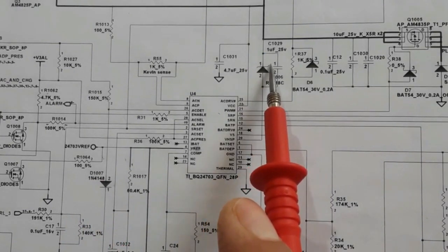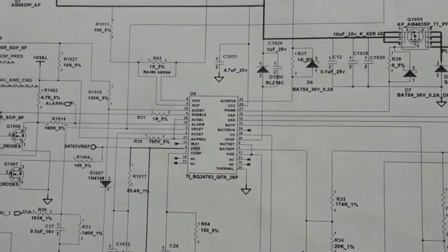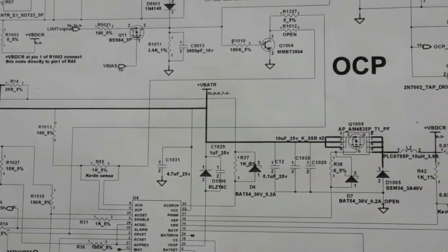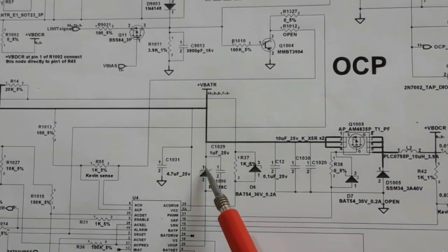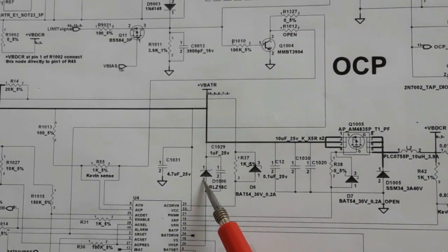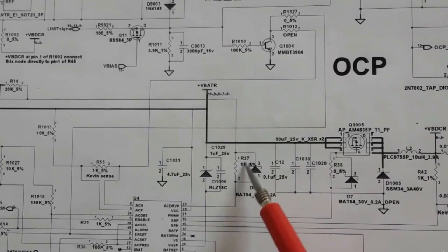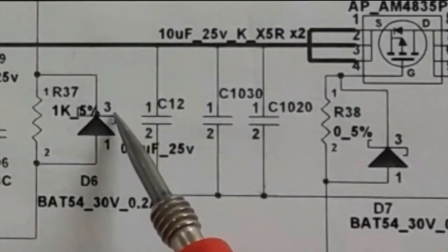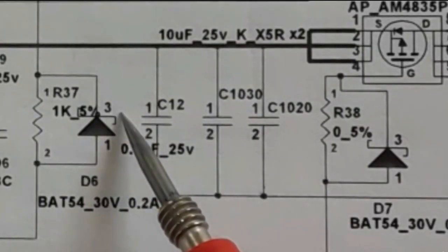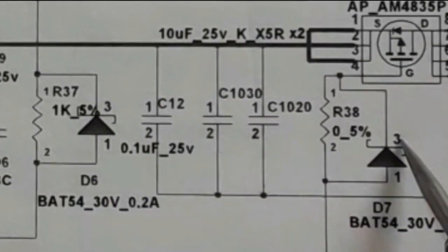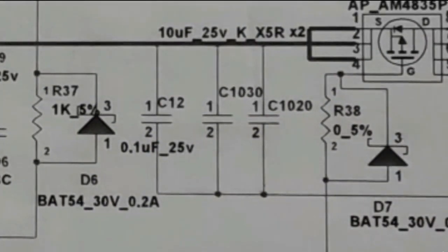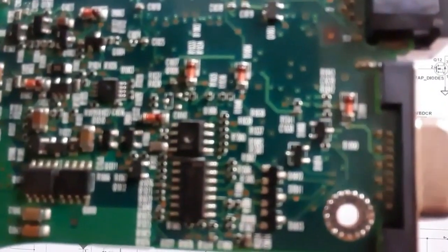If you want to check this diode, you should use the same working principle. You can use the multimeter with the continuity option. Okay, so we're gonna see another type of diode, as you can see, with 3 terminals. We have 3 here, meaning 3 terminals. Okay, this is another type of diode. This is like a transistor, the same shape as a 3-pin transistor. So let's check in the motherboard.